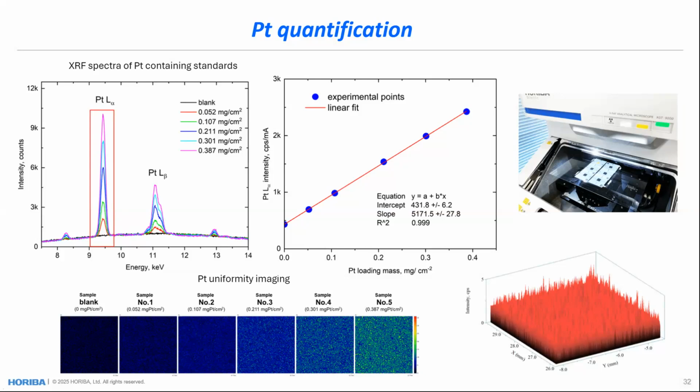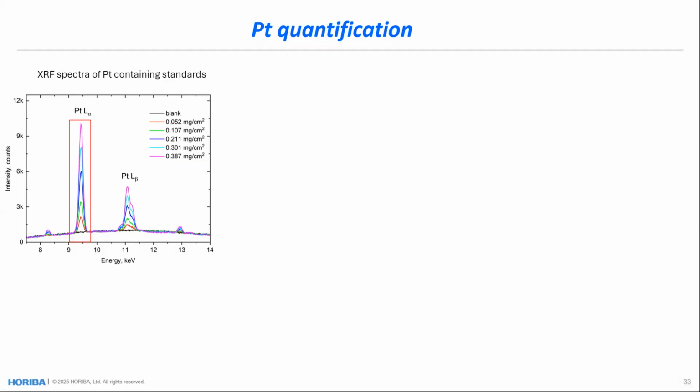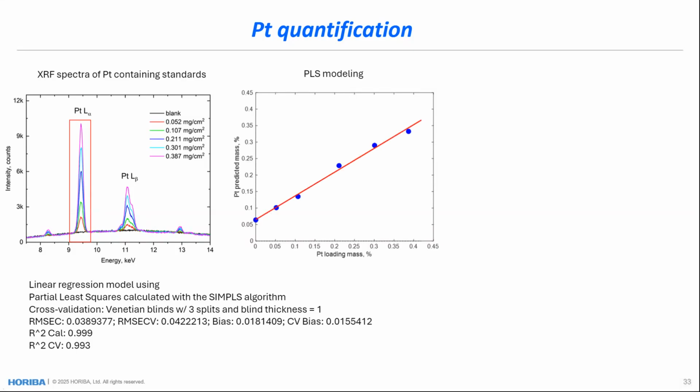However, if we apply this calibration curve, we don't know what the error is. How much error happens with the sample if we apply the calibration curve? So the next technology we can offer you takes the same spectrum and does the exact same things, but we apply partial least squares analysis. PLS modeling gives you a very well done R square, like 0.999. However, this technology allows you to estimate the error in our calibration, and what our error estimation would be if we apply this particular calibration curve to this sample.